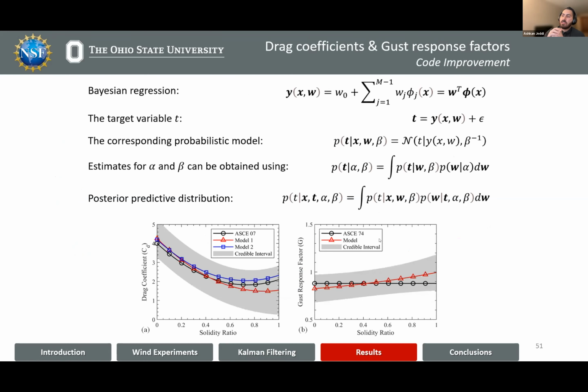And to update the ASC suggestions using the estimated values in this study, we implement a Bayesian regression approach. The benefit of this approach is that without discarding the existing knowledge offered in the ASC manual, we can provide improved estimates. These updated suggestions are illustrated in this slide, and we have provided two sets of suggestions for the data with and without the data associated with the experiments in the transfer direction for the drag coefficient.